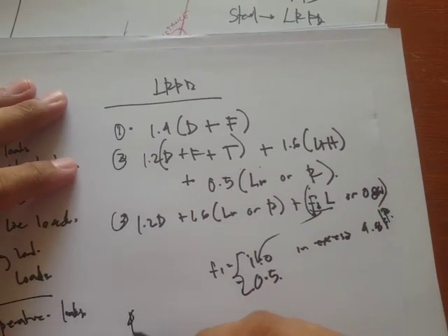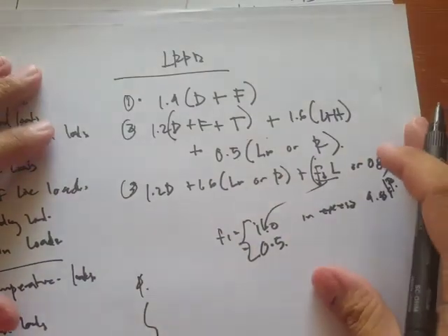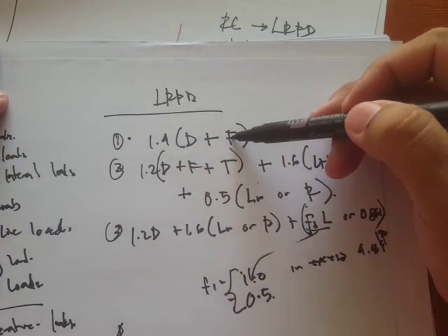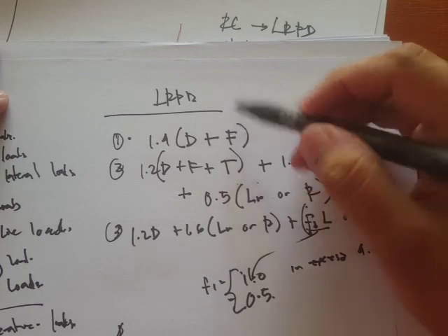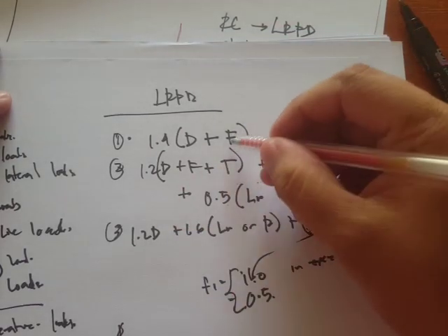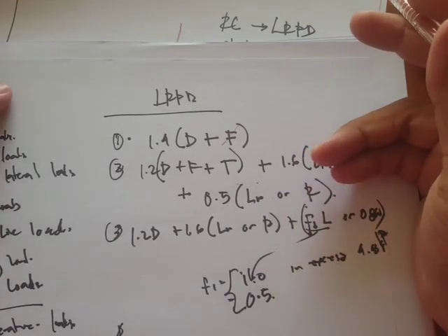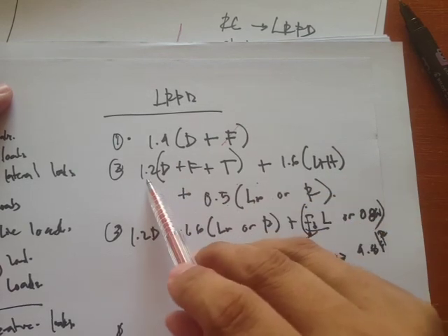And we have up to 7 load combinations. It just means that if we have, let's say, a dead load only, then you can cross this out, so the computation does not include this F. If you have dead load plus live load, then you just say 1.2 dead.